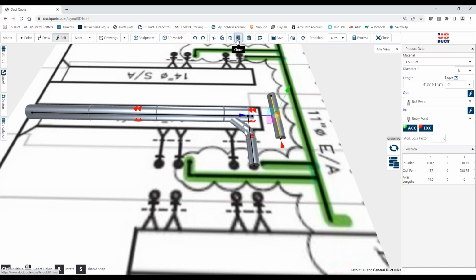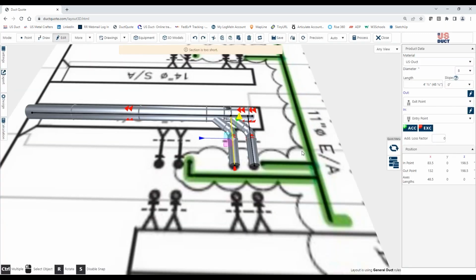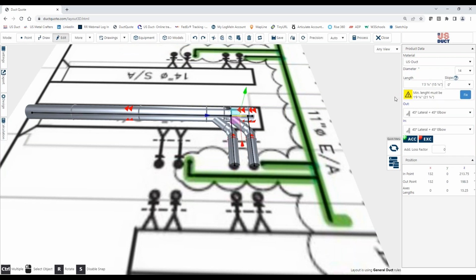Well, if I take another 8-inch drop and try to fit it in on top of where they have things drawn and let that connect, we're going to be told that this does not fit. Okay, so if I now look at how much extra room we need, well, basically the difference between 15 and 21. So there's 6 inches that have to be dealt with. Well, for a hard connect, an 8-inch connection moved 6 inches off center, you're going to have some difficulties.